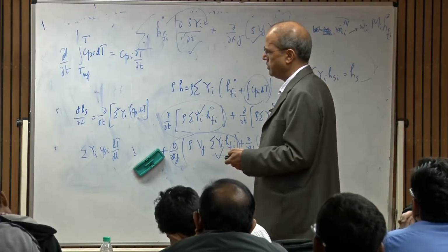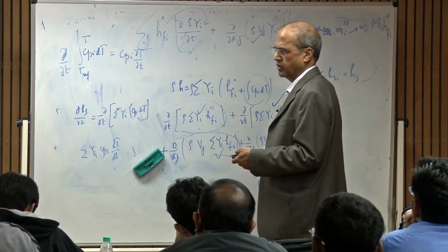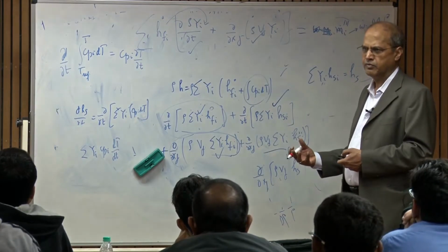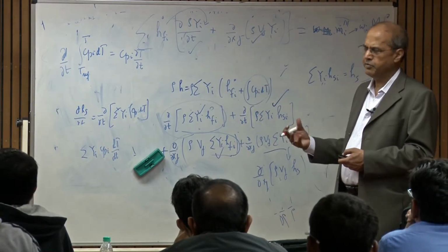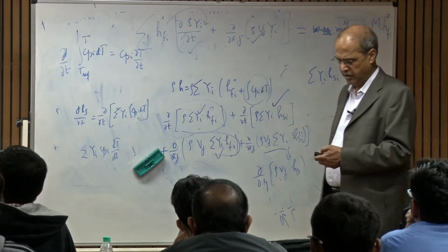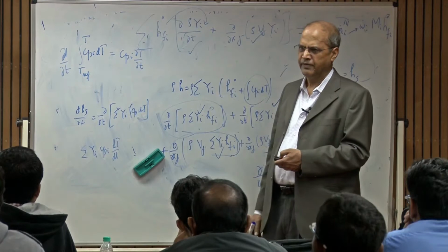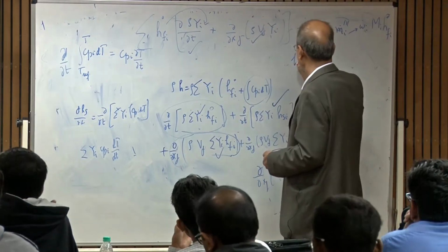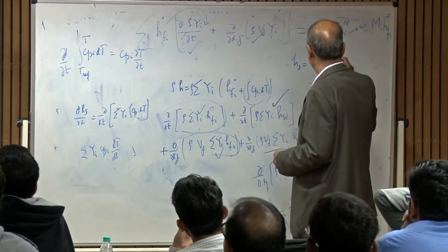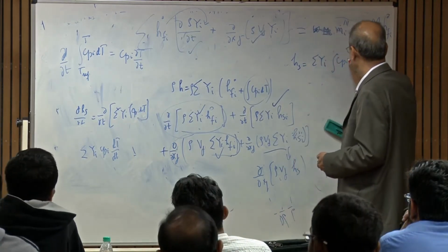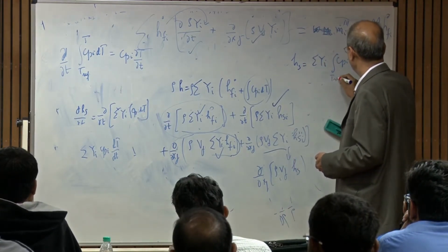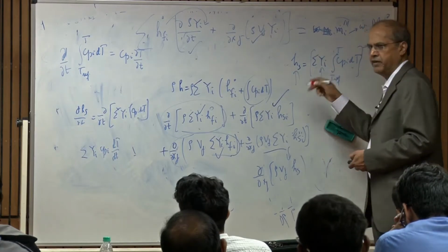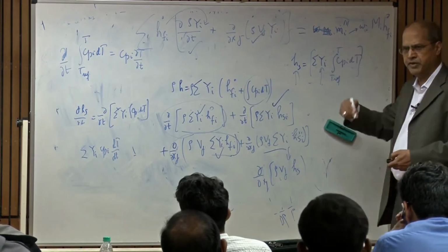So think of this equation as, okay. What is actually the common practice is that many of the software packages don't solve this equation for temperature directly. They solve it for Hs, okay. Then Hs is, as I have written there, the sum of yi times the integral of Cpi dT. So once you know Hs everywhere, and of course you know yi from the species equation, then you can find temperature everywhere from this equation.